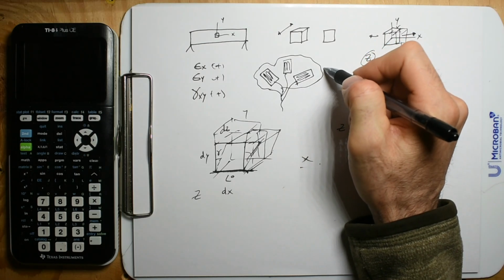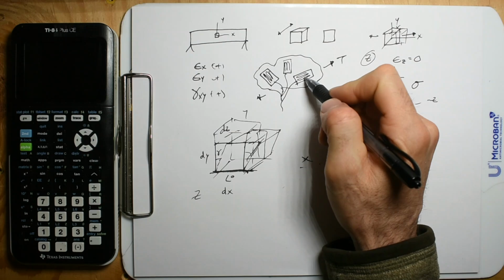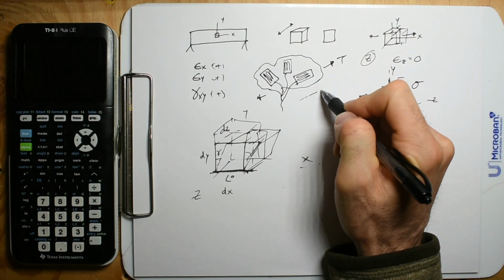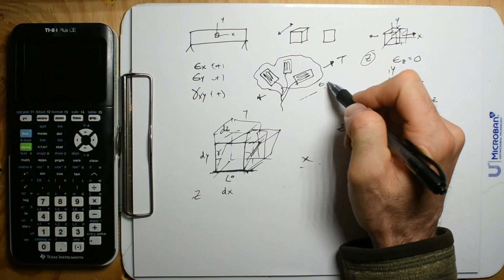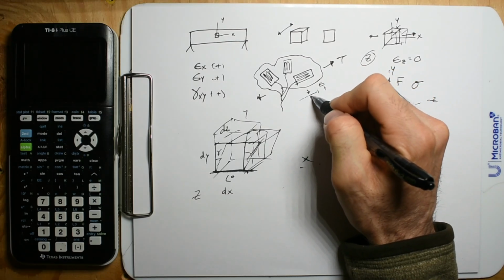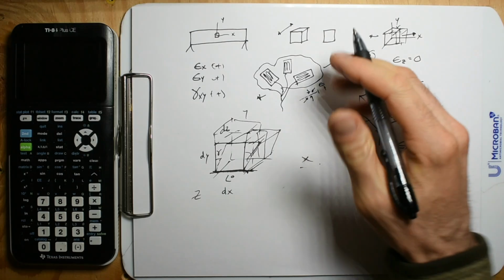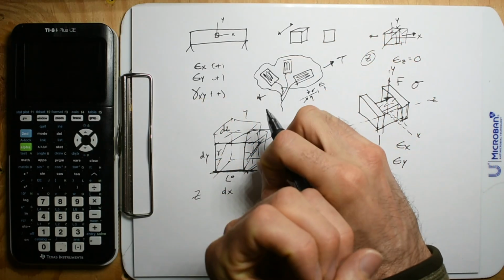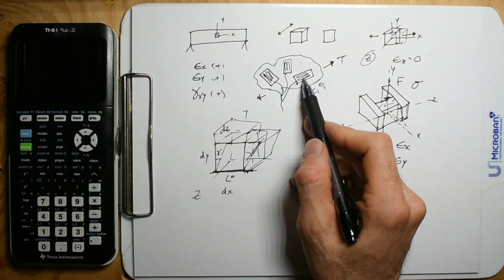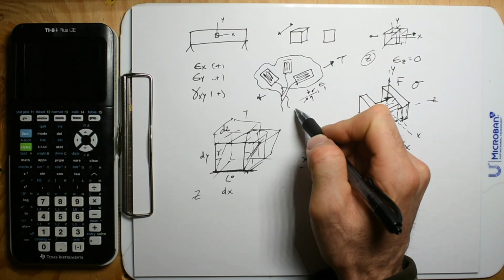And if I have axial tension in this direction, guess what's going to happen to these wires? They're going to change in length in this direction. That's going to be a strain in that direction. But while it's changing length, Poisson's ratio says that wire is going to reduce. It's going to get thinner. You know what I mean? And when small wires get thinner, their electrical resistance is very sensitive.